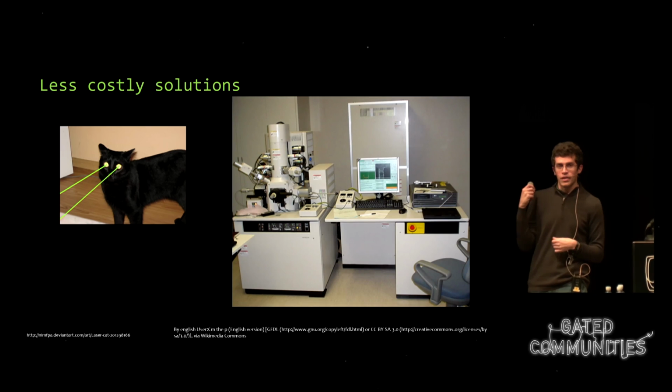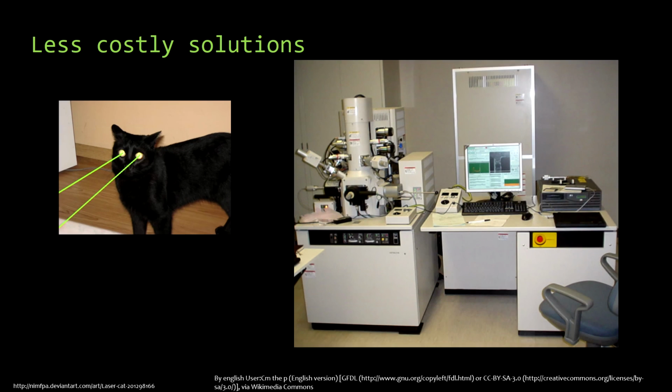This is a focused ion beam machine. It's a cool beast. It can take a chip that's already been fabricated, and it has an electron microscope in there. It actually shoots little ions into it, and it can rewire small parts of the design. It can't do major things, but you can do small things. This is done on a per-chip basis.